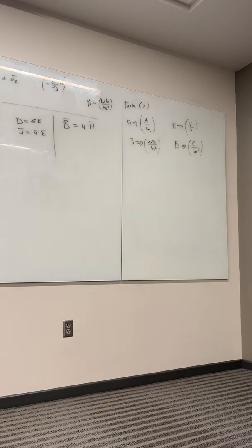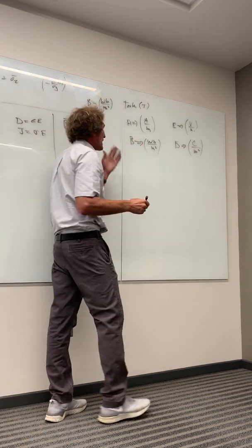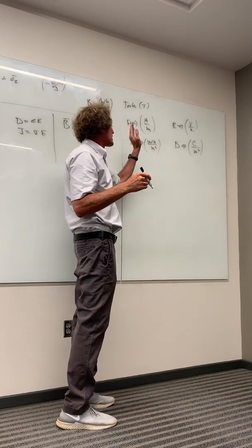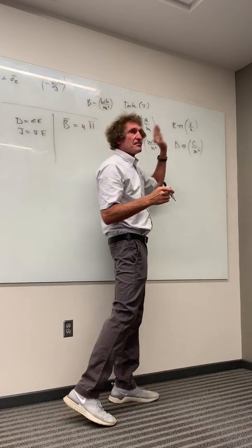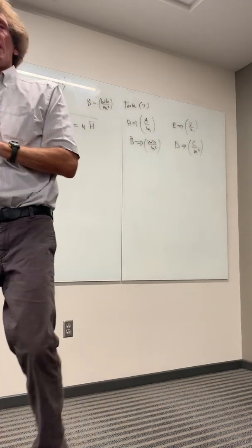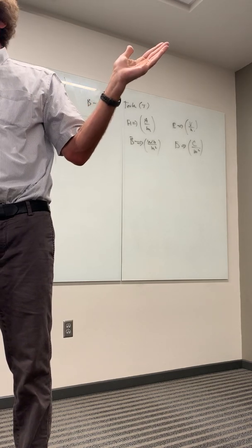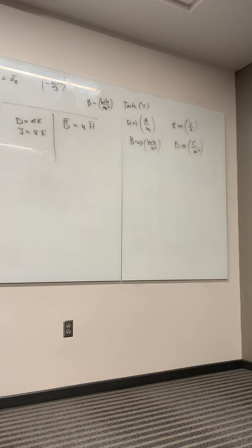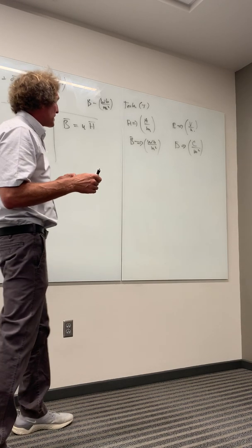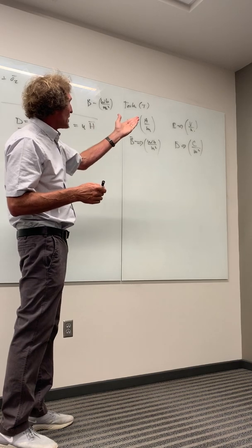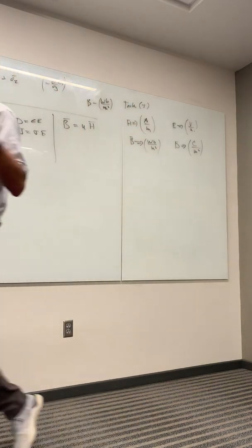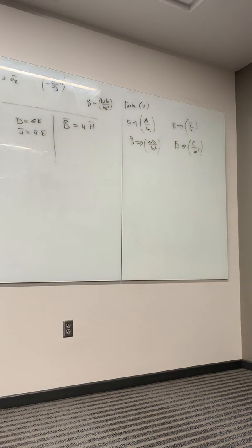But there's similarities in all these things. H and E are very similar. If you think about it, it's amps per meter, volts per meter. This you can think of in a lot of ways as a current. This you can think of as a voltage. I mean, it is per meter, but believe it or not, there's a lot of similarities that you'll see in the problems we do with these. You're going to see later that the ratio of E to H is a constant in the atmosphere for any propagating wave, and it's called the intrinsic impedance. And you would think there would be an impedance related. If we have volts over amps, V over I, that's R, or impedance in ohms, right? I'll get to that later, but I wanted to mention this.